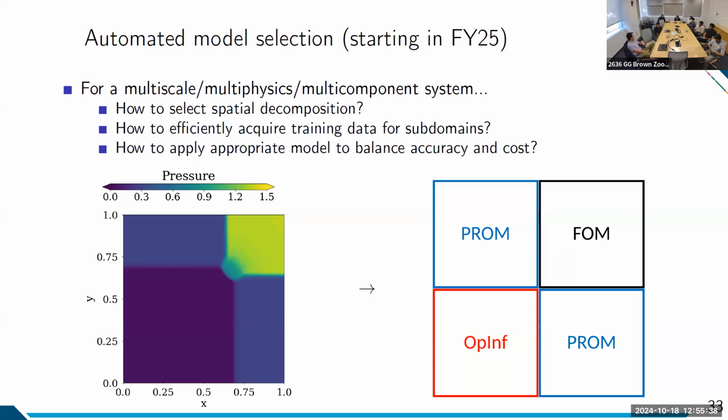In some instances, you have that decomposition chosen for you. If you have a bolted assembly, obviously you mesh the bolts, you mesh the plate. But for fluid flow systems, it's not as clear. For that combustor, maybe you decompose it into the oxidizer feed tube, the flame region, and the post-combustion region. But like I said, you want to decompose as little as possible. Your runtime will always get worse the more you decompose.